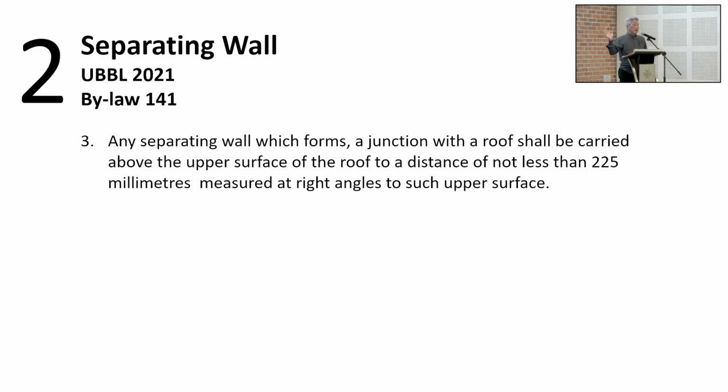Right? This is now a wall that is required to be fire rated. A party wall doesn't say that it needs fire rating. The party wall just describes the physical properties of the wall with regard to its solidness, its minimum thickness, and the acoustic properties. Now, if that party wall is functioning as a separating wall, it shall now require fire rating.